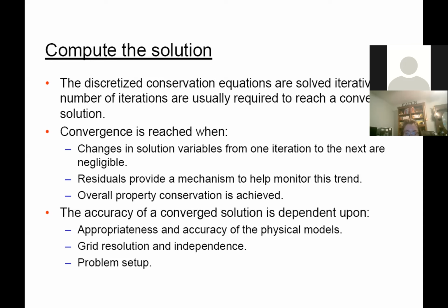I don't know if we had a fluid project. Some semesters I give a fluid project for pipe flow. Remember, we use Excel iteration to get the solution. Some classes I did, sometimes I didn't. Okay, similarly, from the initial guess, right? Your initial condition, basically initial guess, your boundary condition might not quickly propagate to the entire domain. It requires iterations. After you iterate many times, gradually the solution doesn't change anymore. So we call it converged. The solution converged. That means the solution doesn't change anymore after further iterations.